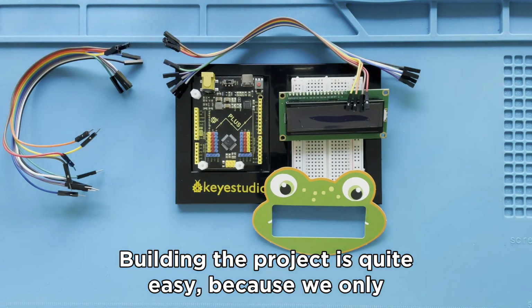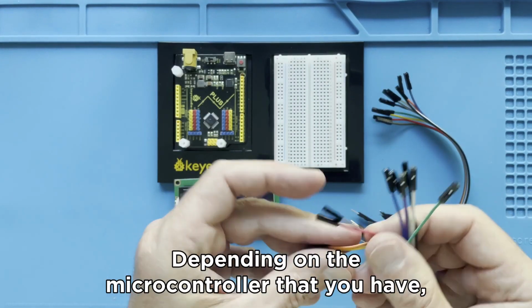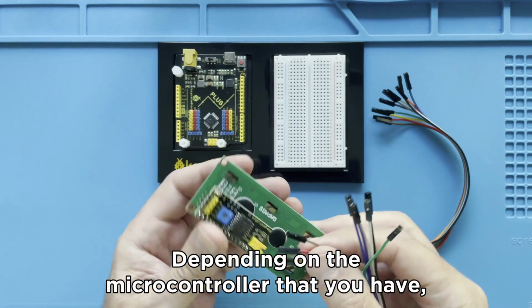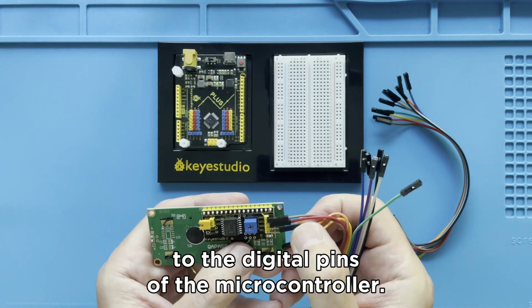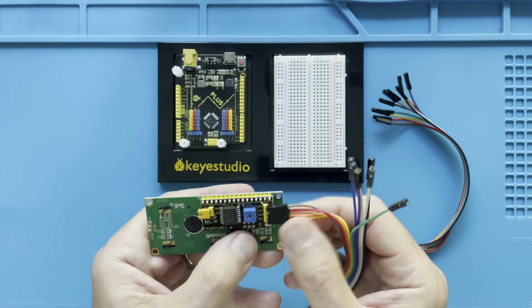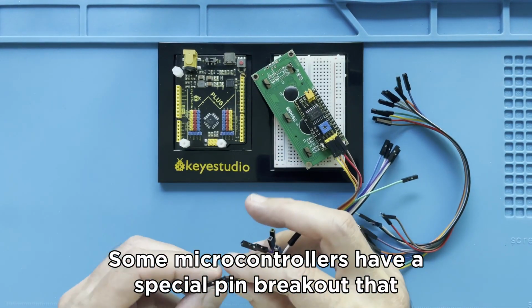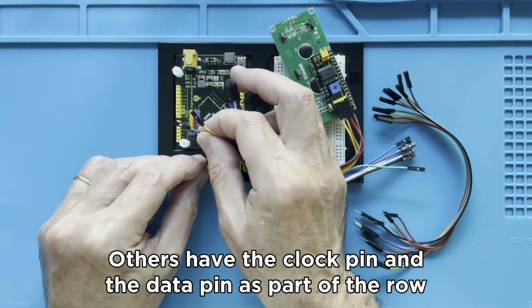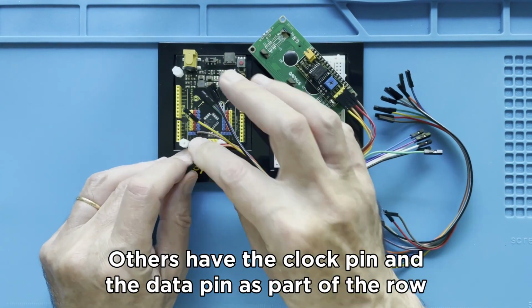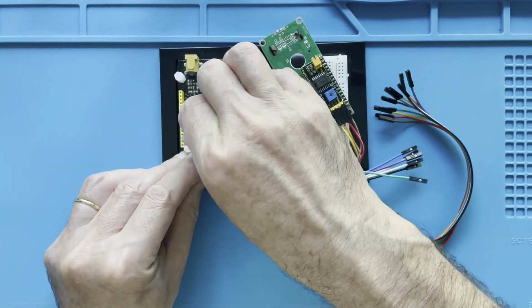Building the project is quite easy because we only need to connect 4 wires. Depending on the microcontroller that you have, you may have to use another connection to link the display to the digital pins of the microcontroller. Some microcontrollers have a special pin breakout that supports the I2C. Others have the clock pin and the data pin as part of the row of digital pins.